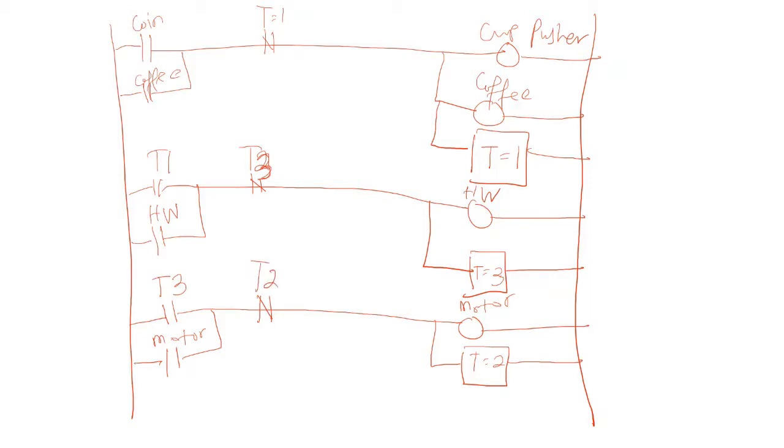Alright, and last one, the T equals 2 timer, after 2 seconds, it will open the mixer valve. So alright, that is your mixer valve. So that's your process, the ladder process for the coffee vendor machine. Alright, let's do it in PLC Fiddle and test.